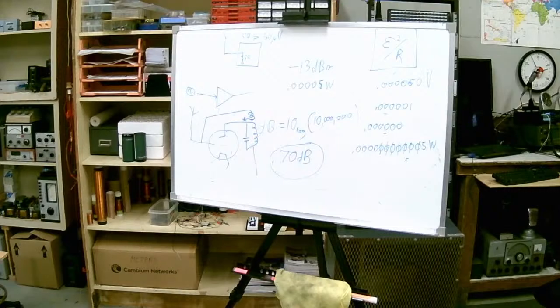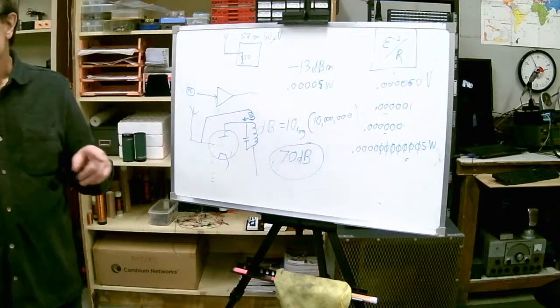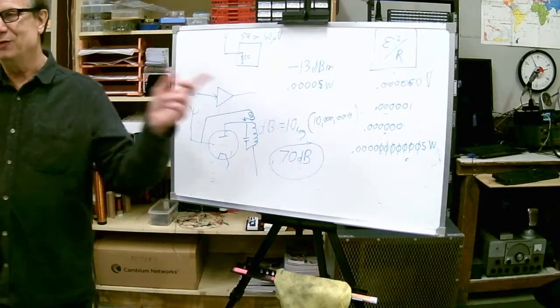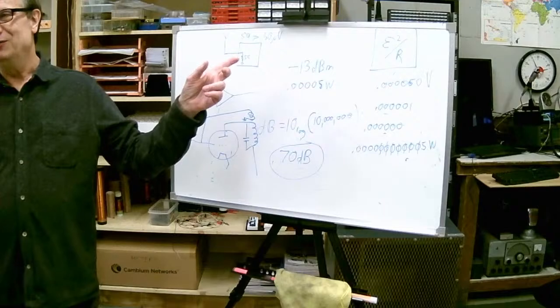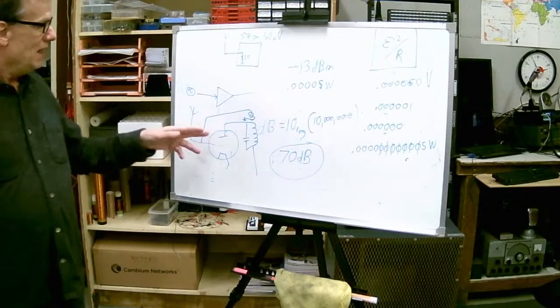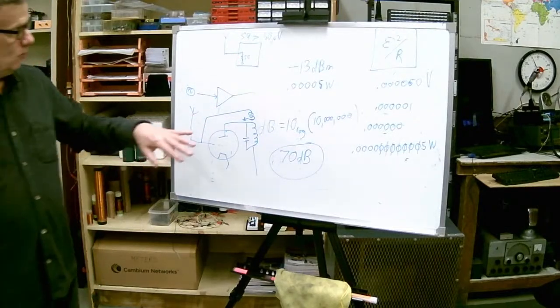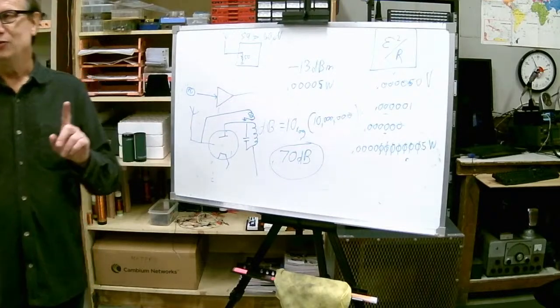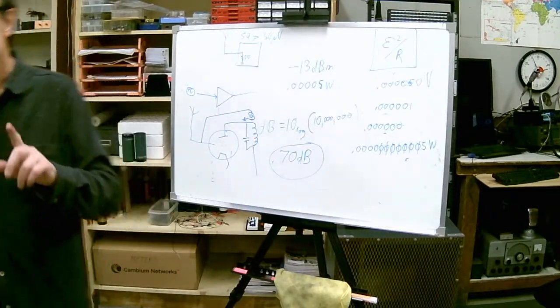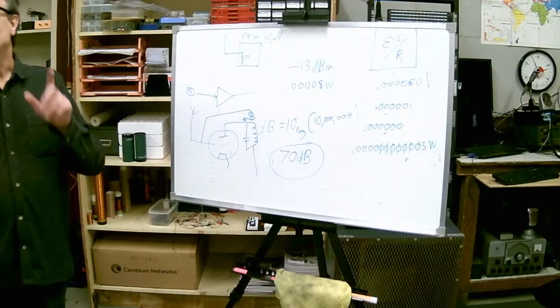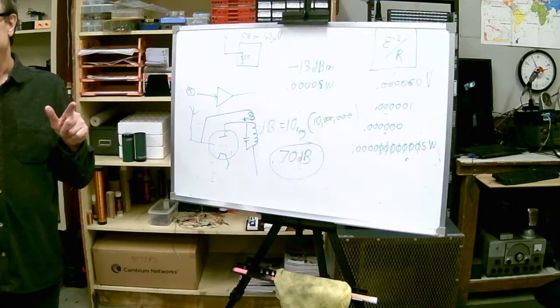Oh, you're right. It comes in through here. Is that it? This small portion on top. Oh, that's it. And what it would do is, remember we talked about negative feedback when using op amps, use negative feedback to set the gain. This uses positive feedback, just enough so this is just on the verge of oscillation. When an oscillator is just on the verge of oscillation, it'll keep going without any input signal, by definition.